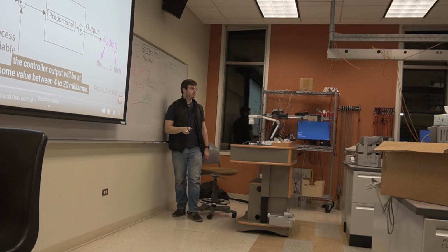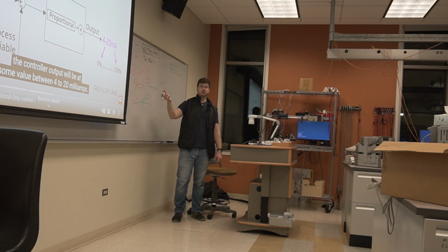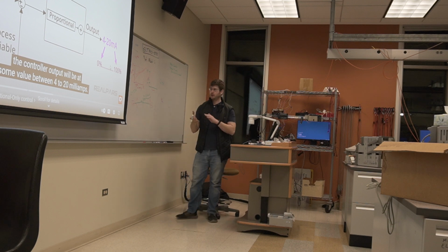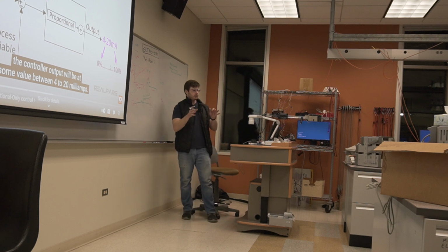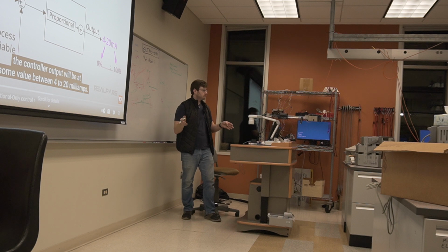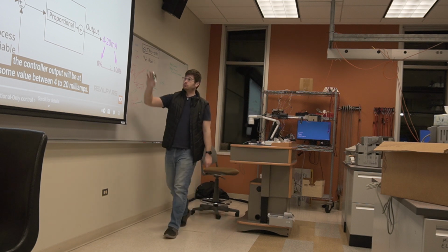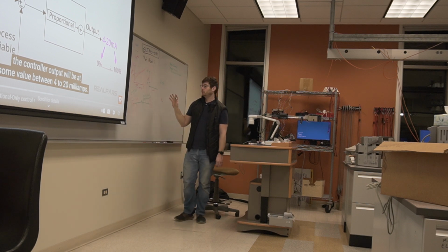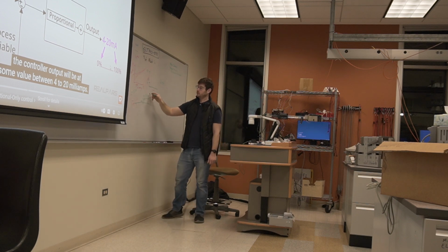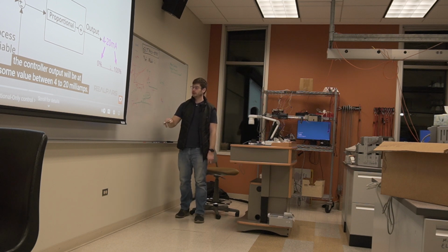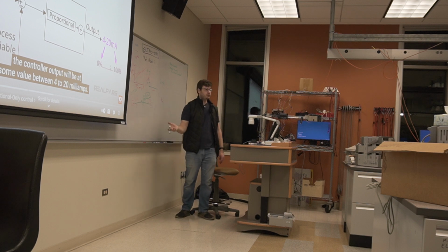It's fault detection. It's industrial ruggedness in play. That's why it's also not 3 or 2, because that's kind of borderline 0. There's a really clear difference between 4 milliamps and absolutely 0 if the line was cut. Any more than 20 would be just passing energy. We're not actually usually powering anything with this current. It's just information. How much current is flowing through here is a data point rather than energy transmission.